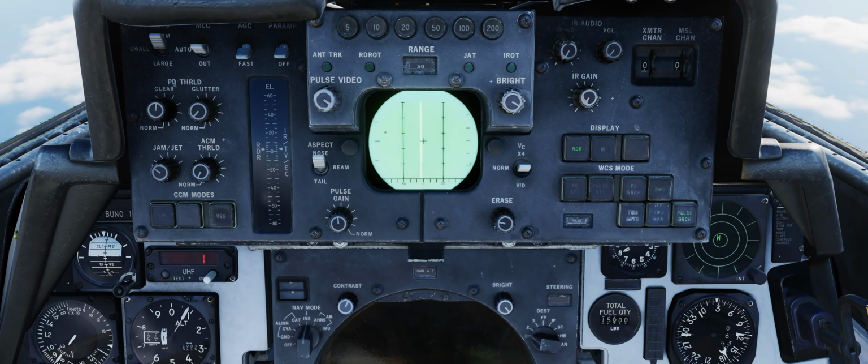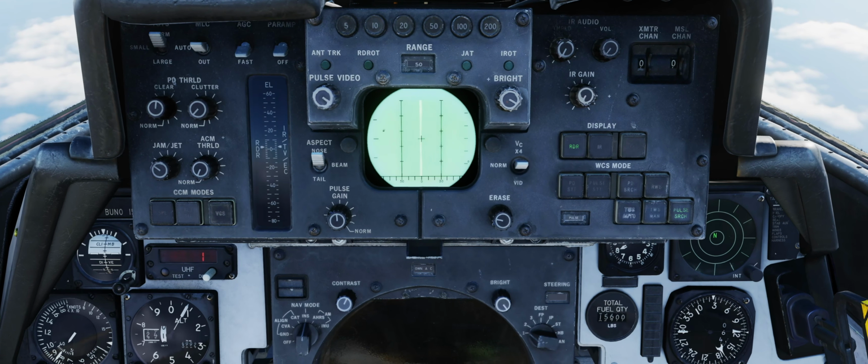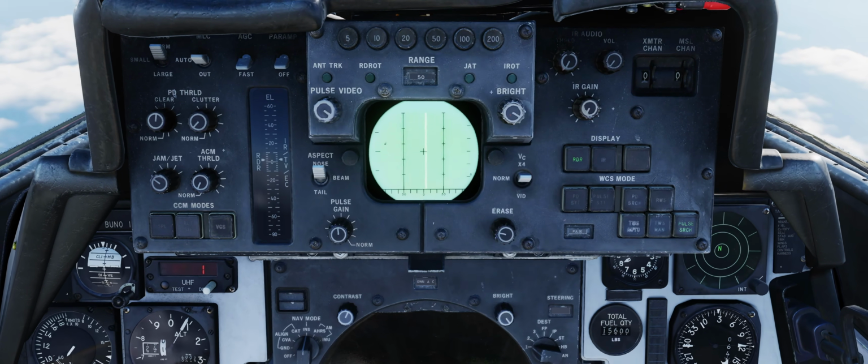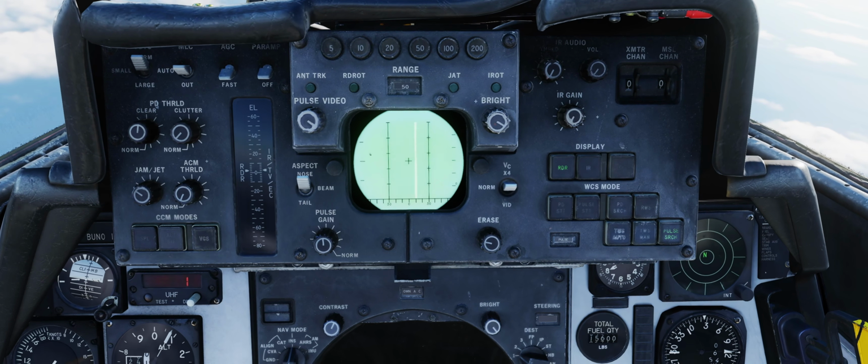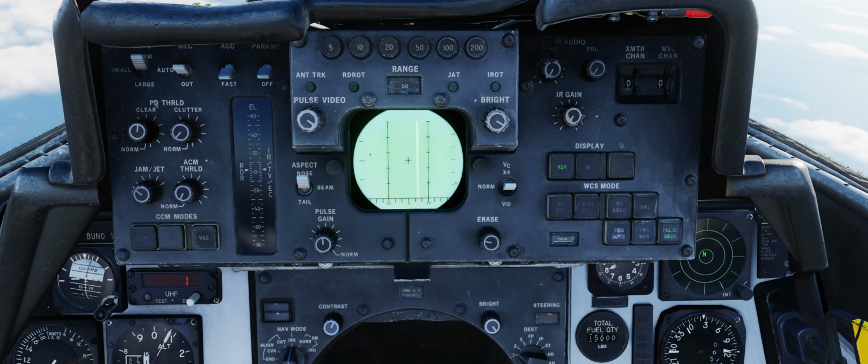At 30 nautical miles, we recap the angles. We are now flying 025-ish, so HCA is about 100, AA is 160, TA is now down to 20. The drift is conspicuous, so better start slowing down a little.